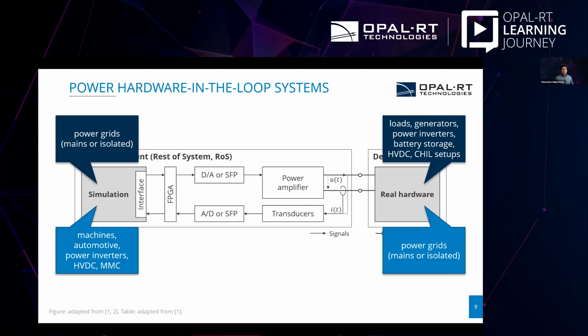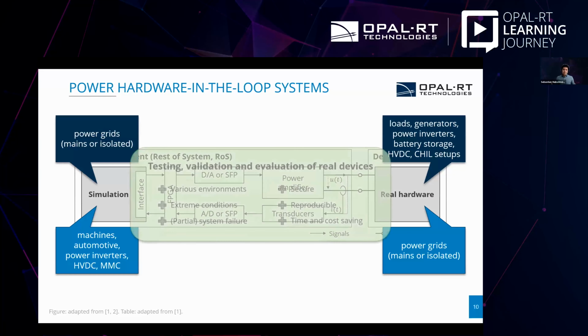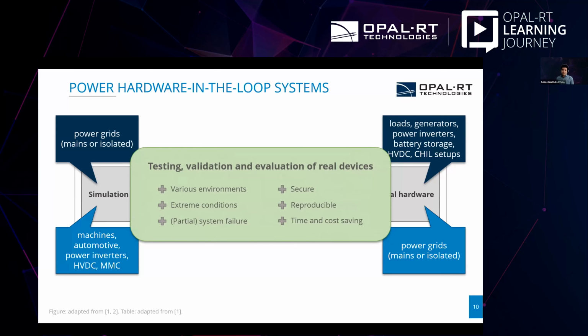Okay, now, after stating earlier that stability and realism can be challenging, why would we actually use PHIL? Where are the benefits for us? Well, I think the benefits are in fact quite huge and overcome the efforts we have in setting up such a test bench by far, as it enables us for testing, validation, and evaluation of real power devices. So here we can test our devices in various environments. We can test it under extreme conditions. For example, simulate even system failures or partial system failures, which we obviously can't do in the real world.